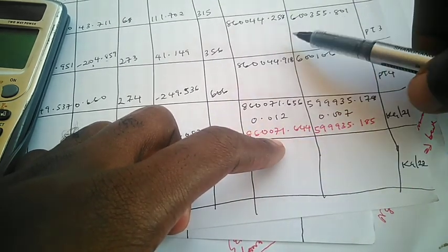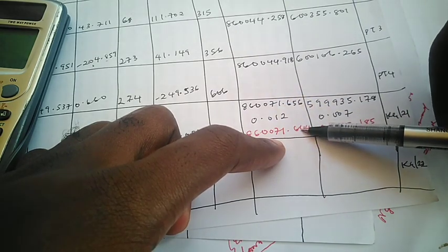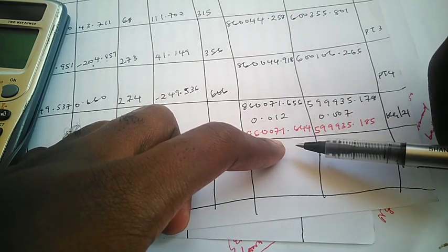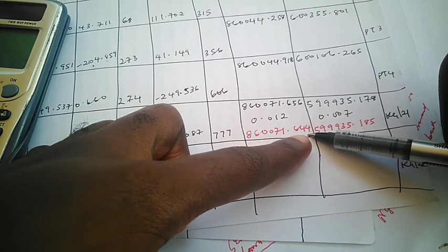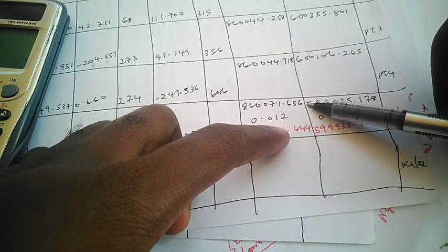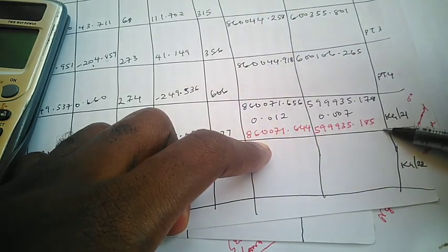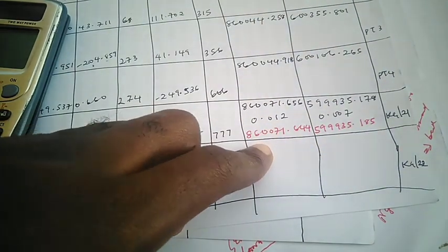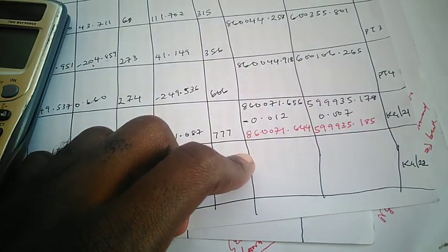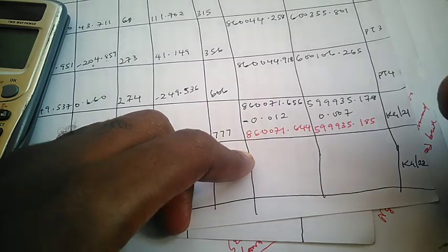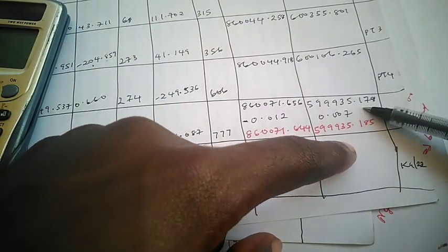I hope you get it. It's like you got 10, but you're supposed to arrive at 8. So you have to move backward 2 steps to get to 8. It's the same thing. So we are supposed to get 644, but we got 656. Therefore, the correction to the control here is minus, so the sign here will be minus. That is clear now. If you don't understand, you can rewind and listen again and you'll get it.